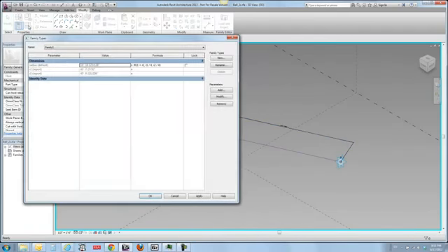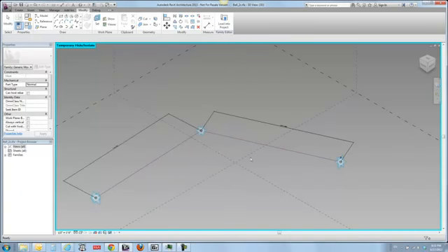And then I've just built a little logic into the radius measurement. Same thing as before, but now I've got a circle being driven by 2 different radiuses. And I have an if-then statement. So if radius 1 is less than radius 2, it's going to use radius 1 divided by 4. And if it's not, then it's going to use radius 2 divided by 4. So basically, I can have this thing detect which one of these points is closer to it, and then make the radius a percentage of that, which gets us our result that we were seeing before.